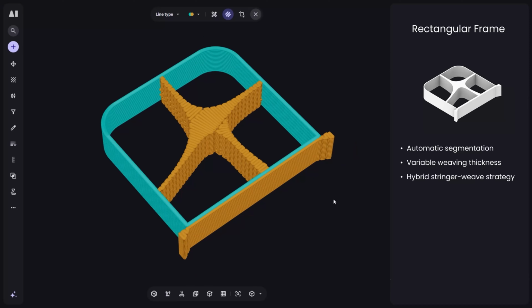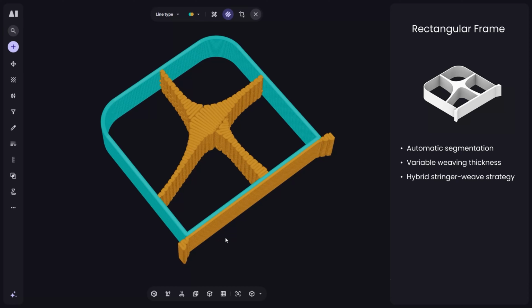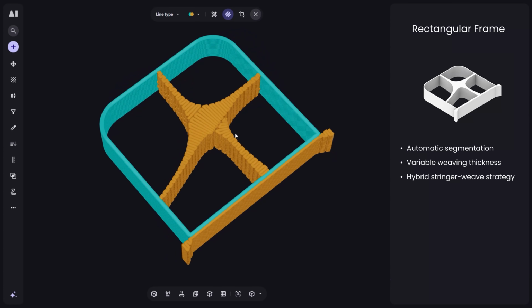And this final example I have for you today is another great example, and this time it is fully automatic. So we can once again use different regions to print parts of completely different settings, different process parameters, slice them in different ways. And this region here, the orange gold infill region, this was done fully automatic. So very impressive. We have this complex kind of funny shape in the middle, and these weaves have been geometrically determined to be printing this way with the settings that we've used.